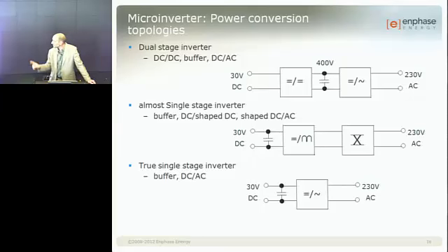And then the only thing we need to do afterwards is to have a switch matrix which can do the reverse of the diode bridge and either go right through or inverse the voltage. Just you go through or you swap. Okay? And when you do this, you get your sine wave output. So that's the topology we've been using to begin with.